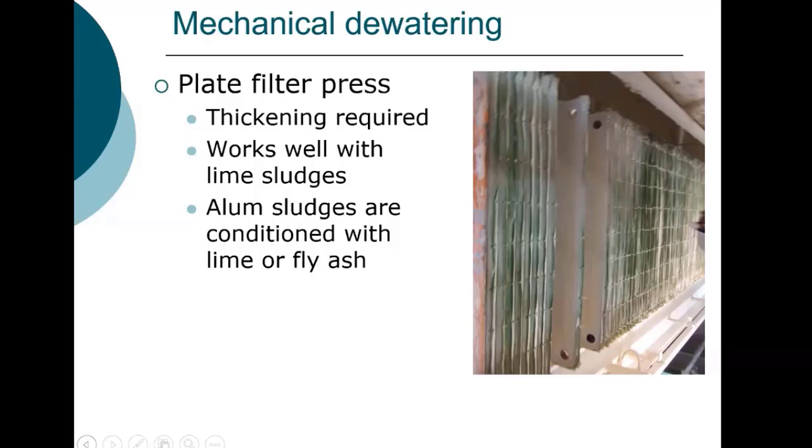So these work by the sludge being pumped into this pressure filter. It passes through a series of feed holes into these filter plates. The pressure is placed on it, forming a filter cake. And then these open and the filter cake falls, in the case of the Lansing plant, into a hopper. And this picture is actually from the Lansing plant.